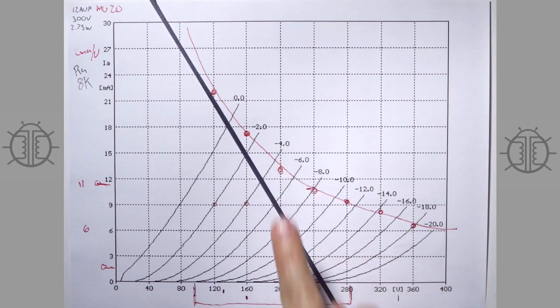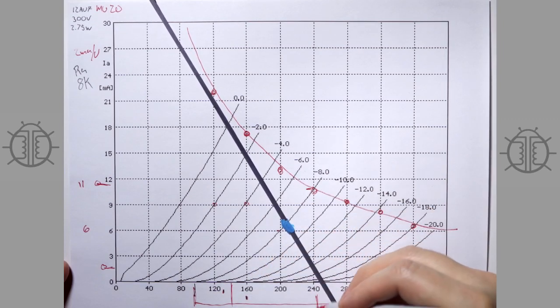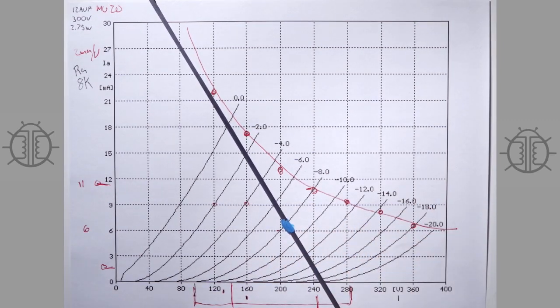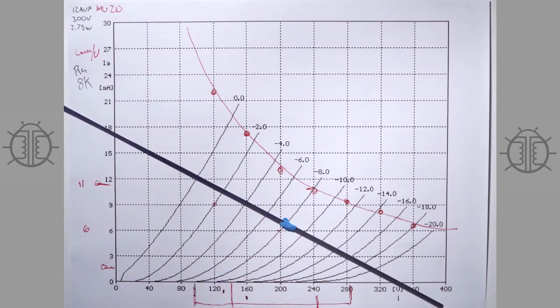And even though your DC operating point hasn't changed, your tube is now in distortion land and not swinging nearly the voltage. You've swung down to where I put my pen, from here to here now, and so you can see how loading down the stage has affected it. So I hope that has demystified these load lines.